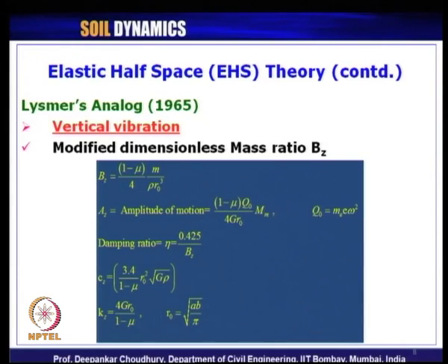Lysmer considered the effect of Poisson's ratio in the calculation of the non-dimensional mass ratio factor, so that the Poisson's ratio effects are already inside the expression of B. So, no need to plot different values of small f1 and f2, the Lysmer displacement functions. We can get a single displacement function f1 and f2 as given by Lysmer.